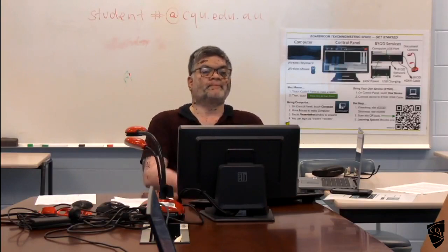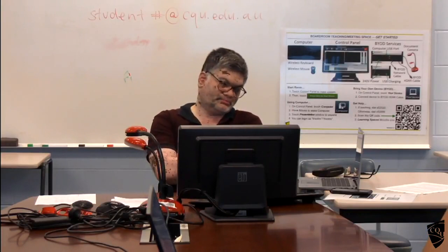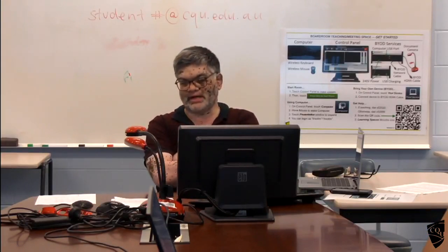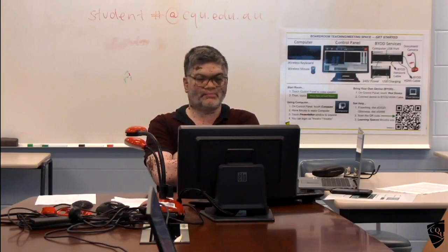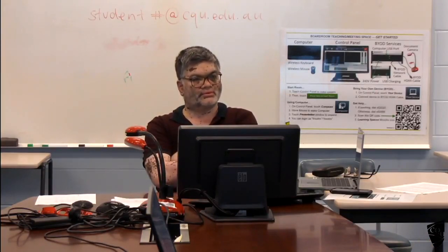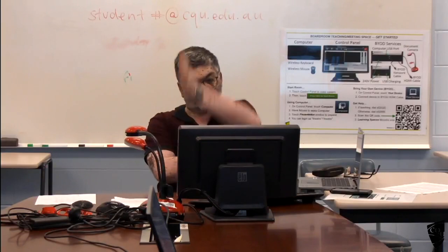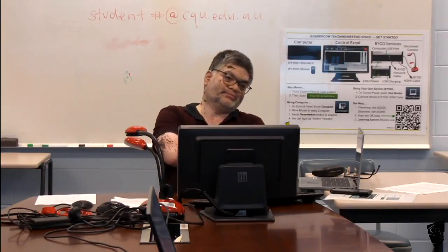Okay, so we have the bending moment diagram. We should be able to draw the bending moment diagram for the design strip. Depending on the number of spans, we should be able to draw the design bending moment diagram. So this is for one direction, for the other direction you also have to do it.